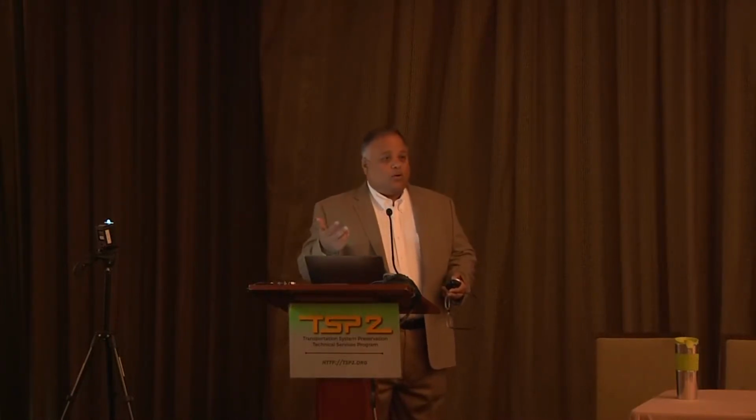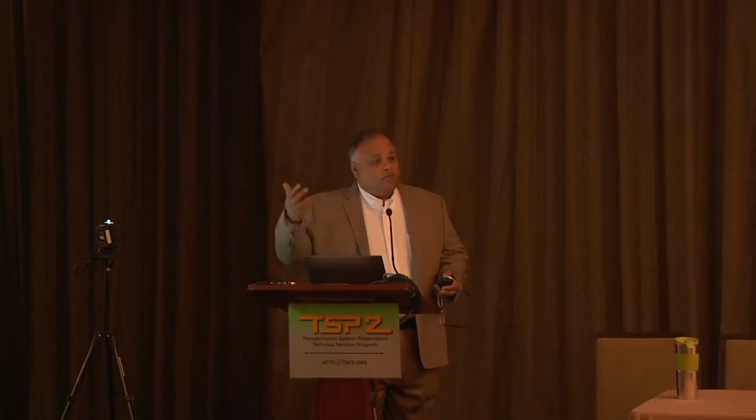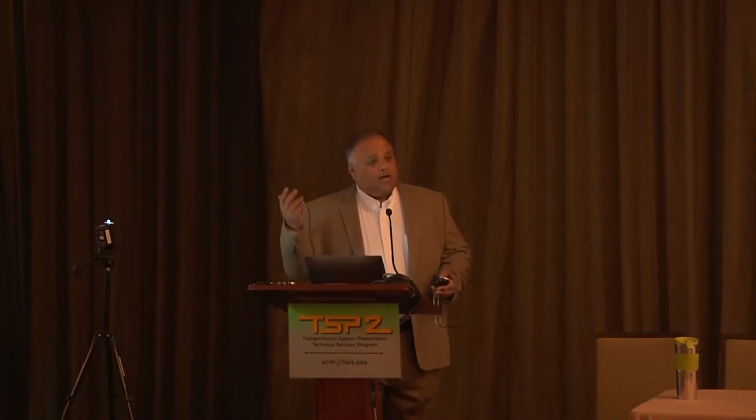Whenever the corrosion occurs, typically what happens is that iron becomes iron oxide. And then the iron oxide reacts with the chlorides and becomes ferric chloride. And when that ferric chloride forms, it moves away from the steel, and then the chloride is released, and it goes back to doing the whole process again and again. So when you have enough chlorides, the corrosion can continue on forever. When you have more chlorides, the rate increases.